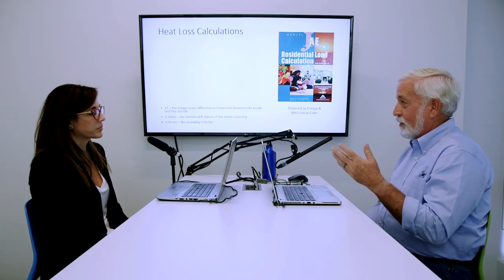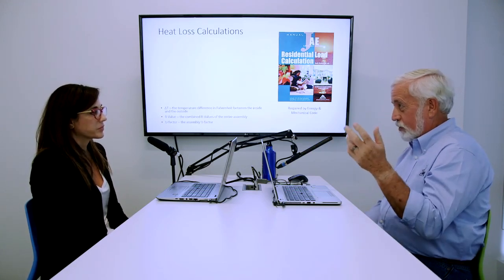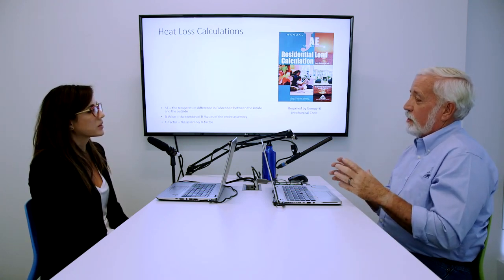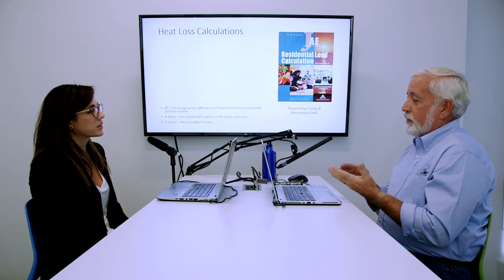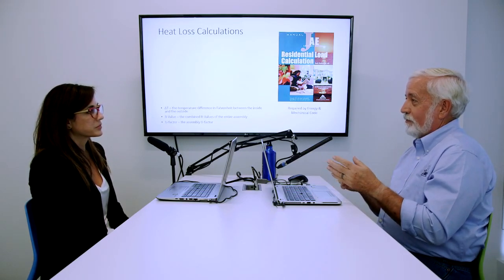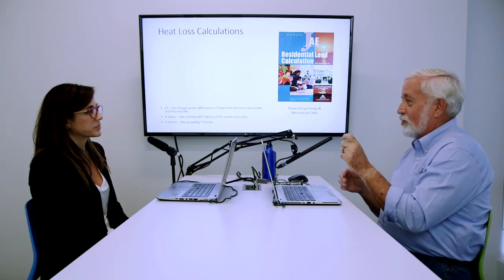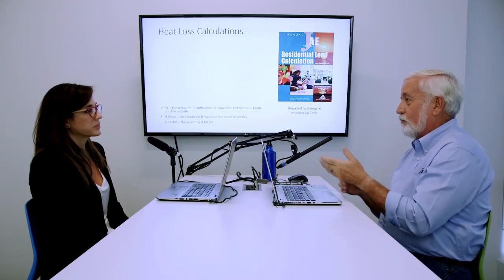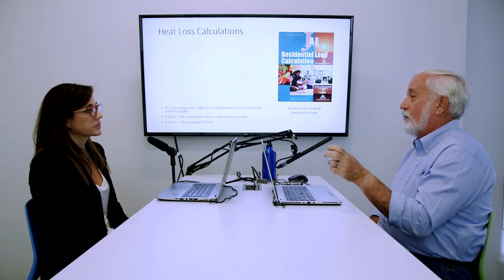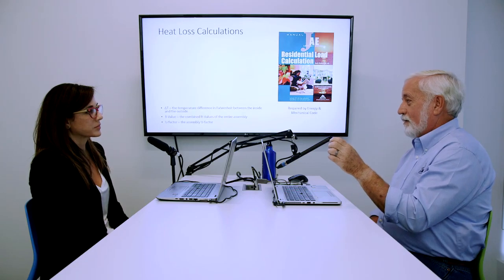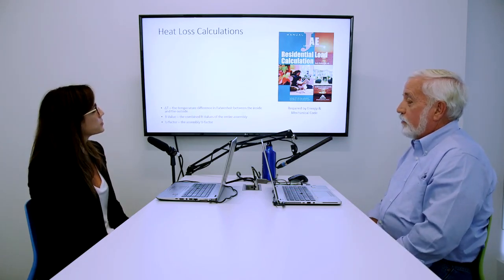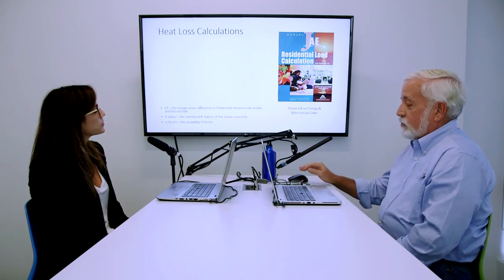Remember we talked at first, why don't we just pick whatever furnace, whatever air conditioner, and just throw it in? Well, as we've studied and talked about building a good thermal envelope and reducing air leakage and all those things, we also talked about how we can have a smaller furnace and a smaller air conditioner when we do these things. So when we do these things, we need to know how to calculate the furnace size, the air conditioner size. And so we use Manual J, which is the industry standard for residential load calculations.